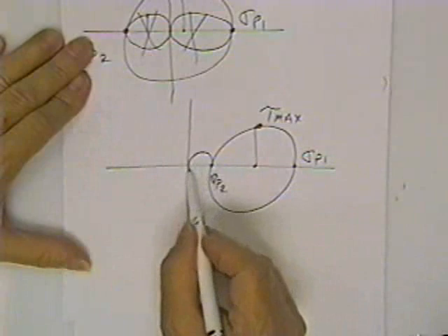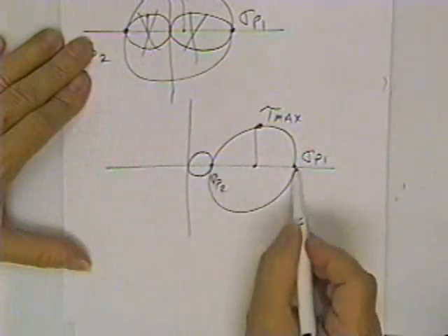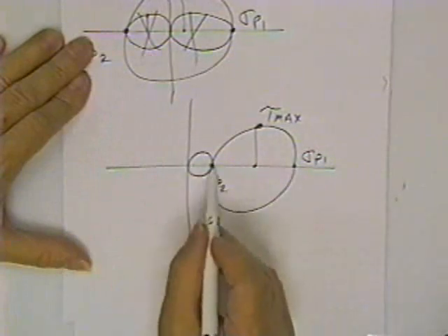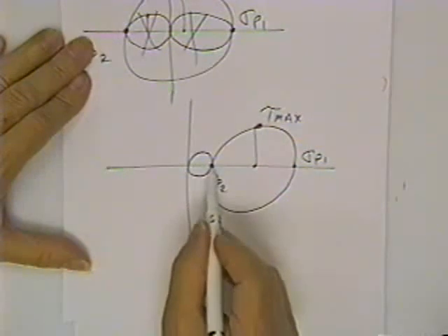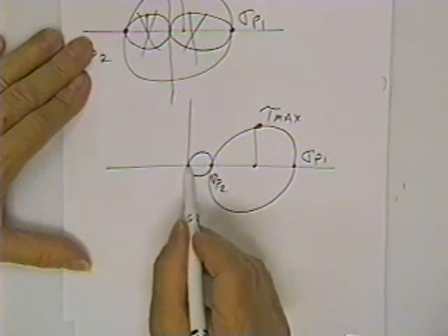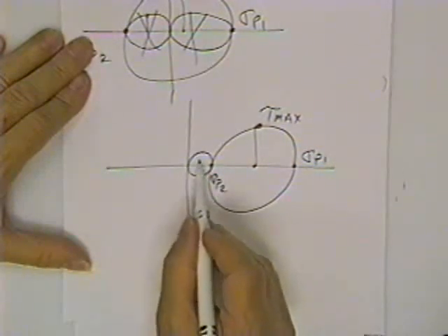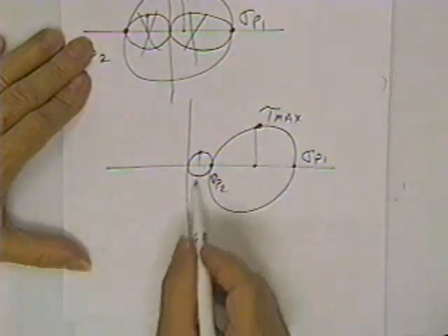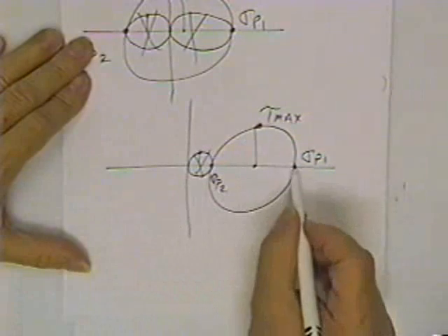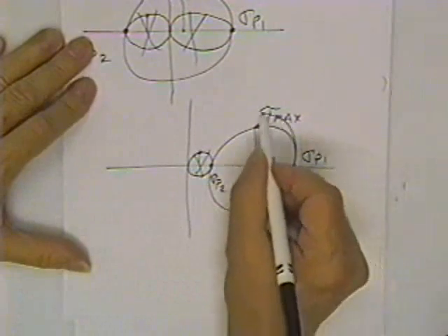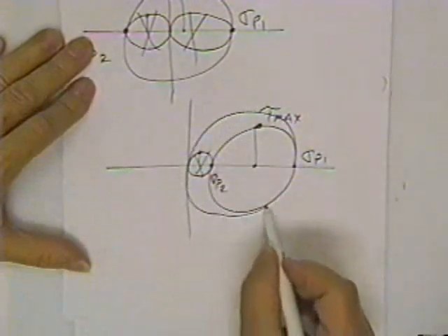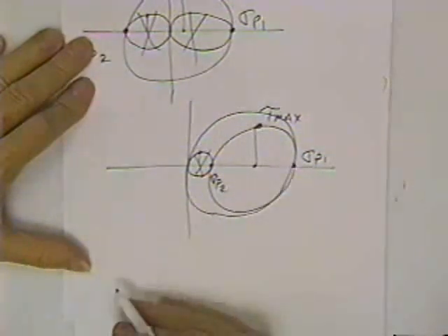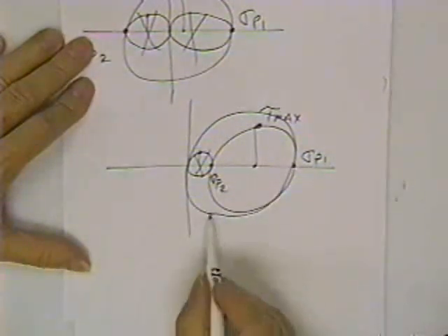There's another circle that goes back to 0. Nobody cares about that circle because it has the same maximum tension, doesn't have any compression, so we don't care about it, and its tau value is smaller than our tau max, so nobody cares about that circle. This is the one that kills people. There's another one that you don't see out of the plane of the drawing.